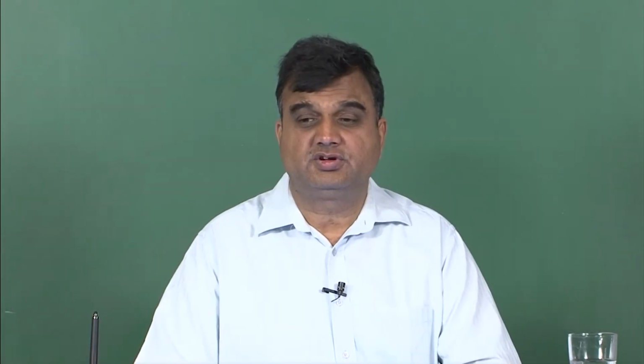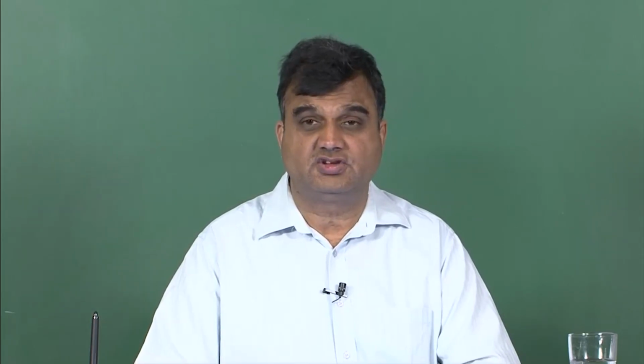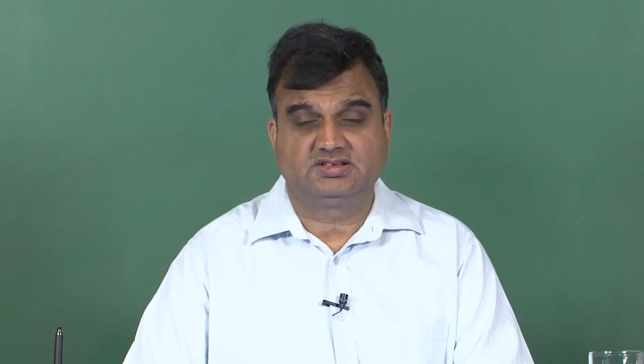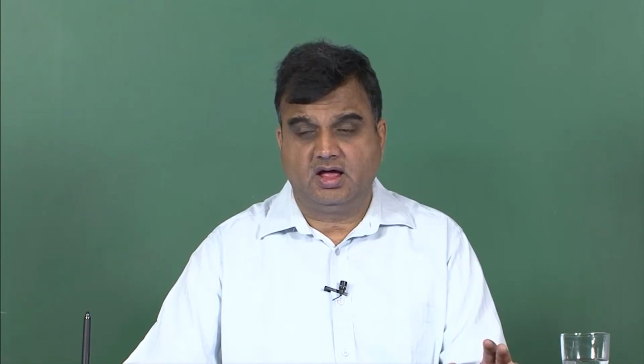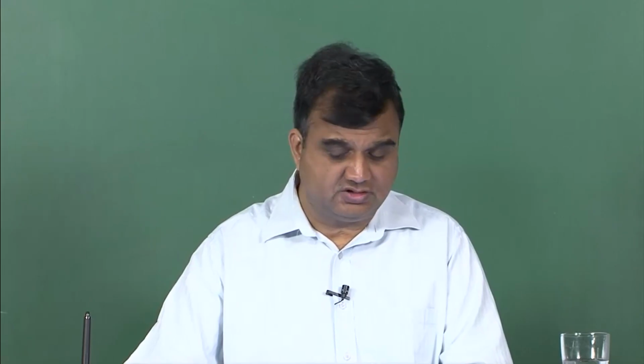Hello, welcome to Introduction to Composites. Today is the last day of this ongoing week, which is the 9th week of this course. We have been discussing the formulation of stress strain constitutive relationships for different types of materials, and we started with anisotropic materials, when we found that it has 21 independent elastic constants. Especially orthotropic material in 3D has 9. Material which is transversely isotropic, that is its properties in a particular plane are isotropic, has 5 elastic constants, and today we will discuss